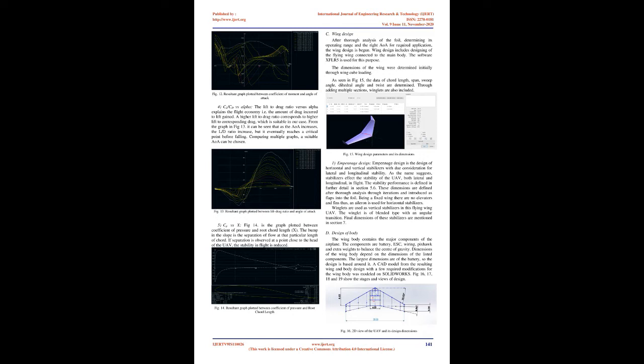According to the specifications, APC 6x4 is the recommended propeller; the diameter of the propeller is 6 inches and its pitch is 4 inches. Fig 1 is a visual representation of the chosen motor. This setup would give a thrust of 1141 grams from each motor at 80% throttle. Since two motors will be used, the resultant thrust is 2282 grams. As the total estimated weight of the wing is 1000 grams, the thrust-to-weight ratio is 2.282:1. This ratio is acceptable for both aerial and underwater traversal.